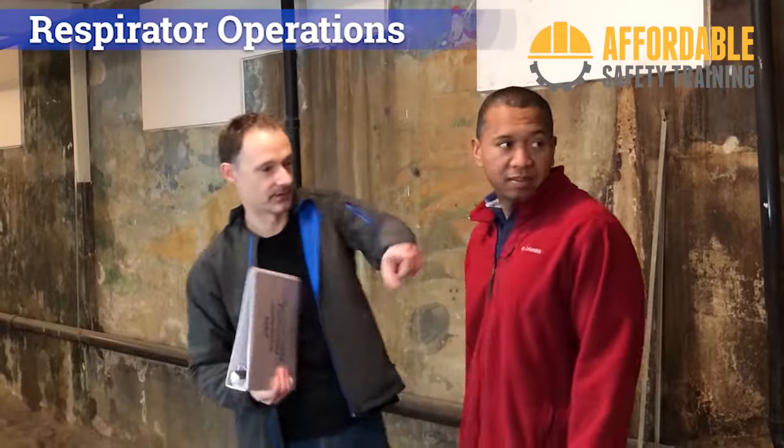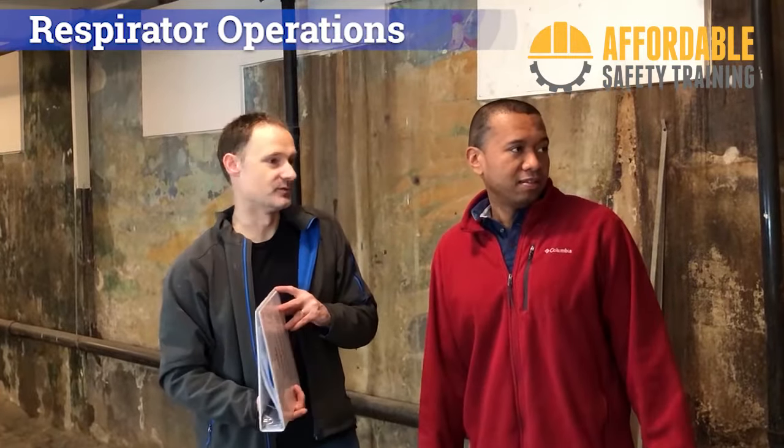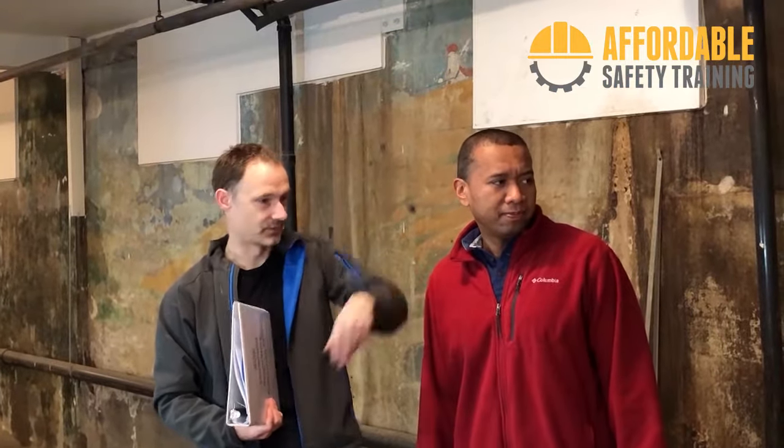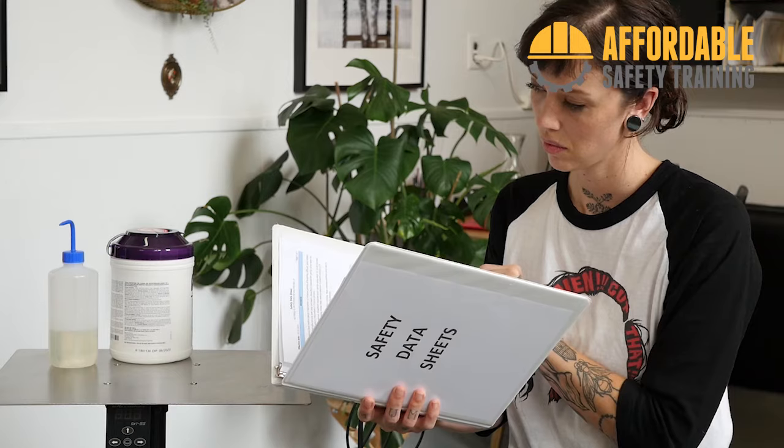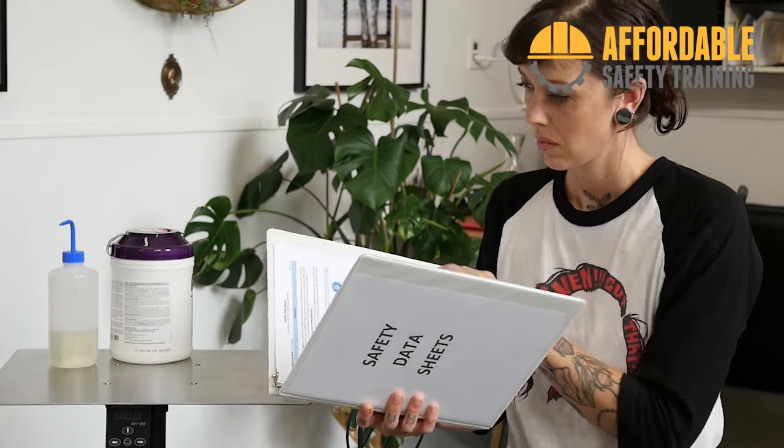Employees must know the types and concentrations of contaminants in the workplace. The company respiratory protection program will have this information. Employees should also be familiar with the safety data sheet for each contaminant.